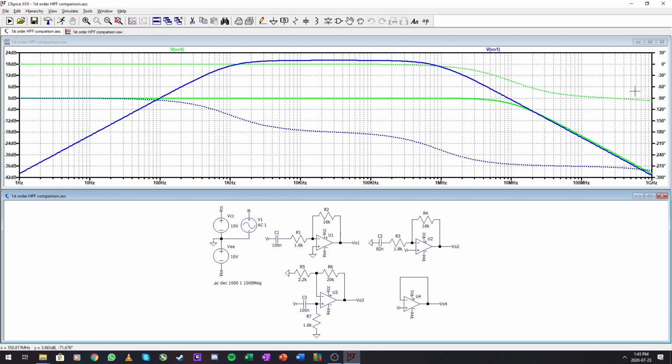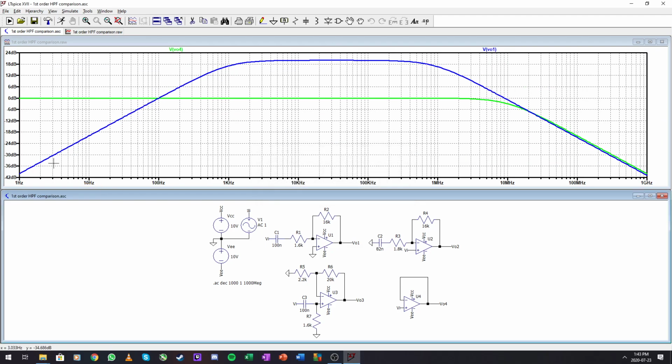You see it will have our cutoff frequency here up until 1 kilohertz, and then we have our pass band, and then at 1 megahertz it will start cutting off again because these ideal op amps from LTspice, their gain bandwidth product is at 10 megahertz, so this moves to 1 mega. So we will have this cut off rate and then pass band, and it will cut off again.